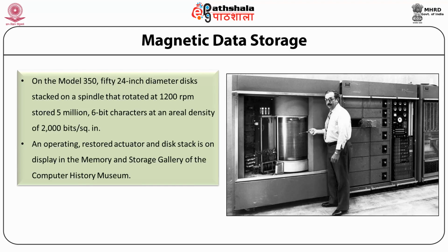One problem with large rotating disks is that they wobble, called runout. To get the head consistently near enough to the surface, it was necessary to force it close using air under pressure pumped to the head.